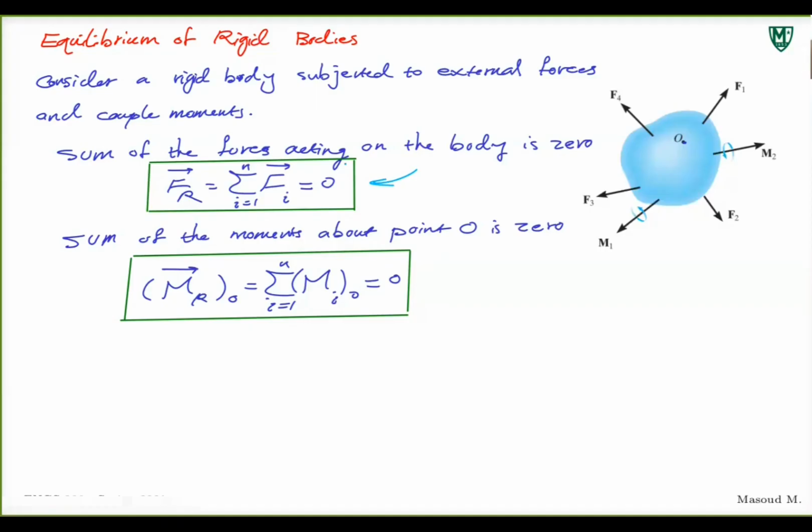Depending on the direction of the force and where it's applied, you might get moments. It's different from a particle, and that's why this second part comes into play. Still Newton's law, the derivative of that, says the resultant of all the moments we were calculating about a point should also be 0 for a rigid body in equilibrium.